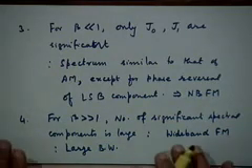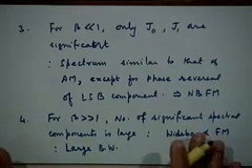But these descriptions of bandwidth are qualitative, right. Small or large is qualitative. A natural question arises, can we convert this into a quantitative value? Can we say this is the bandwidth? Now that's a slightly tricky situation here. Why? Because theoretically, no matter what the value of beta may be, whether it's small or large, how many components are present in that series expansion? Infinite. So theoretically, or quantitatively, the bandwidth is always infinity, right?